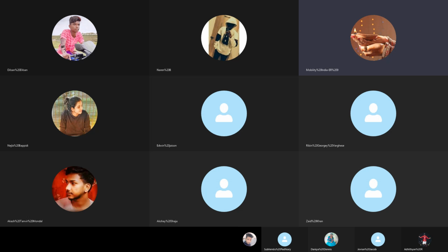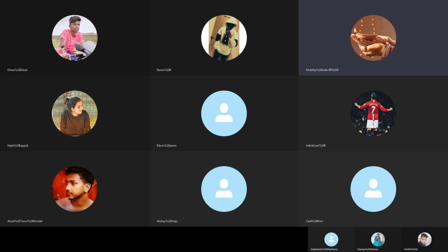So this is the 4-band color code that we had discussed. We had initiated the discussions, and you people are already clear about the 10 different colors that are there. BB Roy of Great Britain, very great wife or a very good wife. BB black, brown, RO red, orange, yellow. GB green and blue, and then violet, grey, and white. These are the 10 standard colors that are used for color coding purposes.